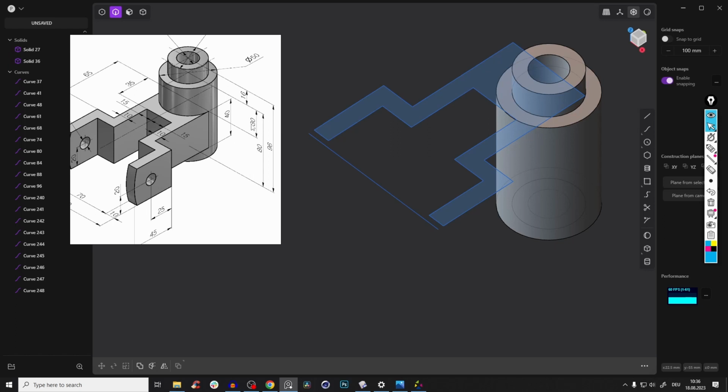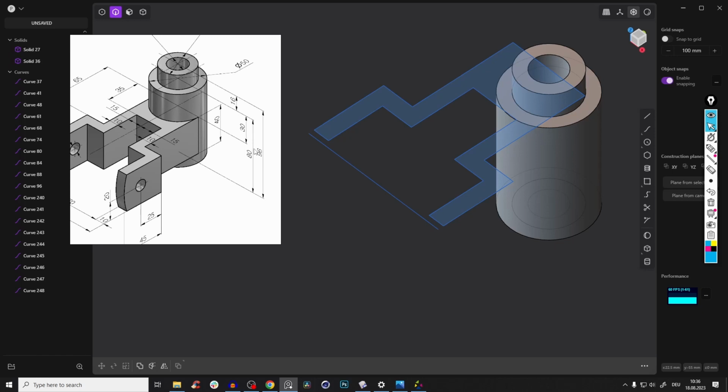So basically, let's do it differently. Let's create here again a construction helping line with the length of 30. And then we can just snap our whole curve sketch towards the end of it. So we just know that this is 30 millimeters away from the edge, and then we can just give it 40 millimeters whole thickness.